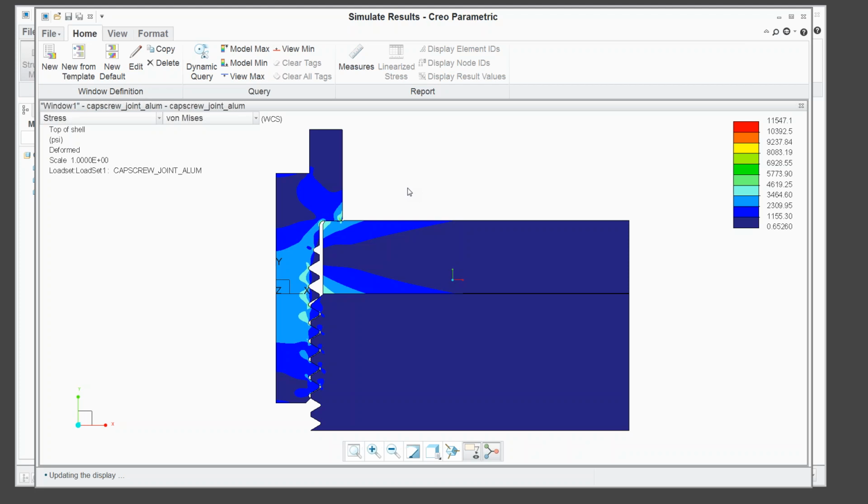You can also do large displacement problems. If you have large displacement and small strain, and I'm thinking essentially with linear materials, like if you were designing a spring or something like that, you can do those problems pretty well. Anytime you use contact, it is by definition large displacement nonlinear. So this was an iterative solution. It took quite a bit longer than just a straightforward solution without the contact, but that's just the nature of contact. Anyway, I think we're about out of time, so I've shown about all I can show here.